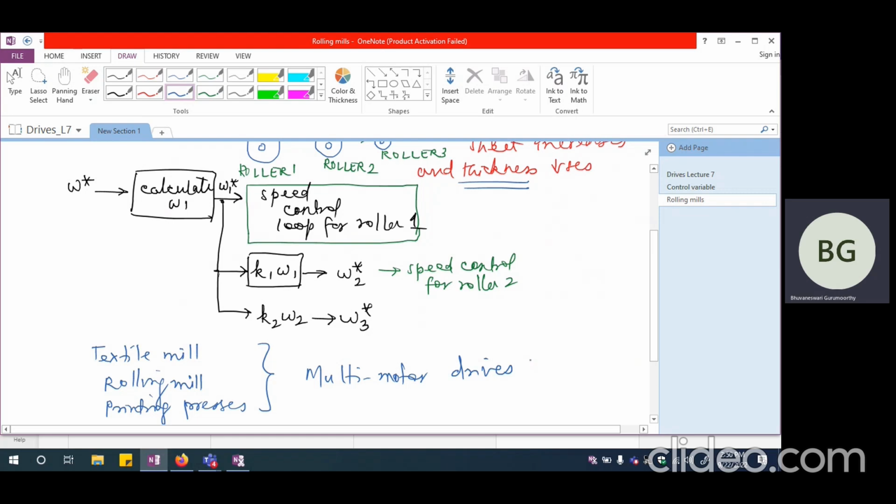So in most of the cases, in most of the industrial environments especially, you are not going to have only one motor working and only one drive unit controlling that one motor. Rather than that, we may have multiple drive units controlling several motors, which all work in a coordinated control format. So that's extremely important when we talk about the control of electric drives.